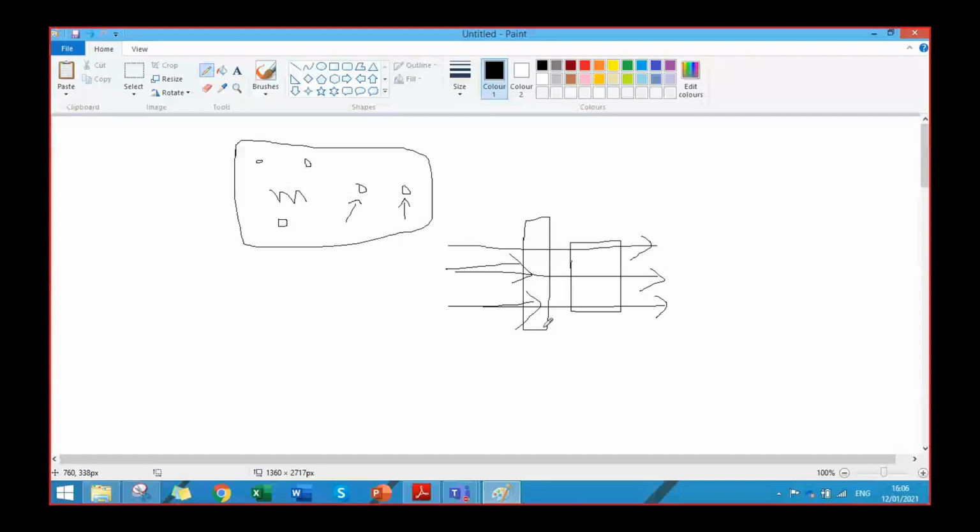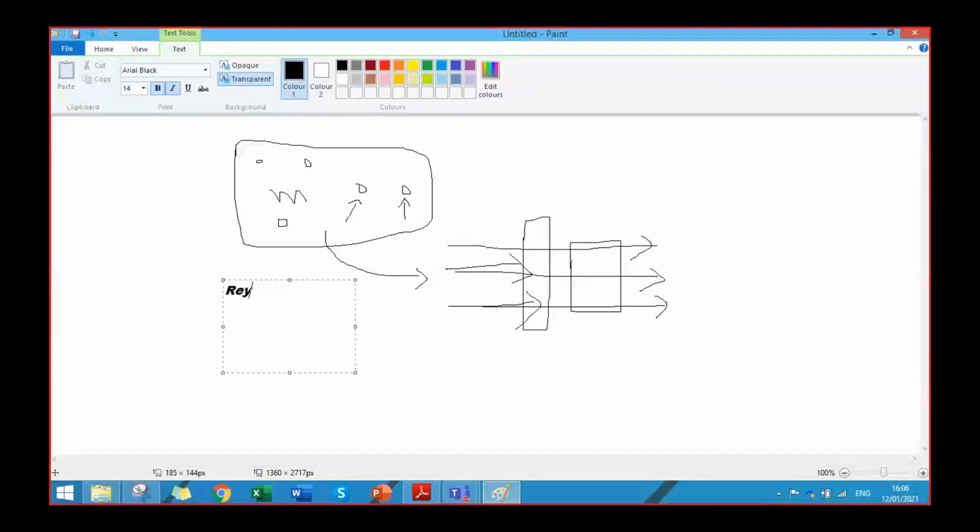So what we need to do is define some convenient mechanism that can help us translate these laws from the system approach to the Euler approach, from the Lagrange approach to the Euler approach. That translation is provided to us by the Reynolds transport theorem, or RTT. This helps us to convert